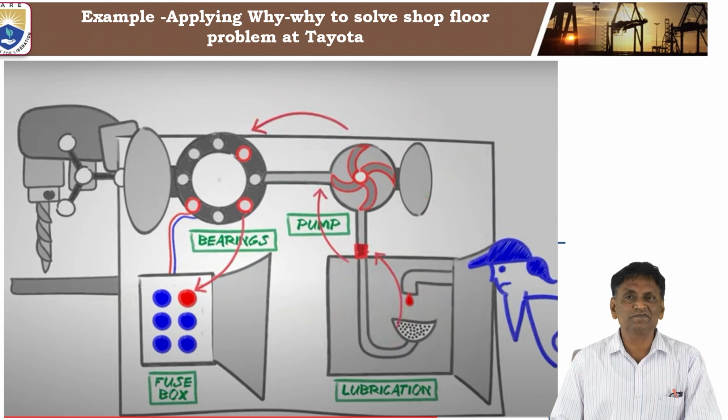In this particular machine, the strainer was not assembled by the person who installed the machine. So all the dirt and metal scraps were going into the pump and damaging it. Now the entire thing was cleaned and the strainers were installed. After that, the machine ran for so many months, six months or so, without giving any problem.